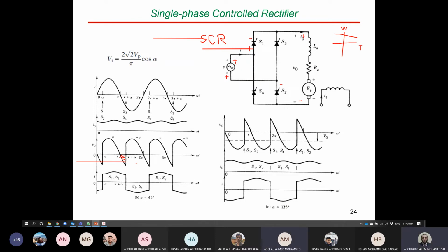Because the average is positive. The average is positive, but why do we care about the average? Why do we not care about the traveling period here? We have a part that is negative. Why will the motor not be reversed? The part is too small to be effective. Small or large here in terms of what? The time constant. Exactly.